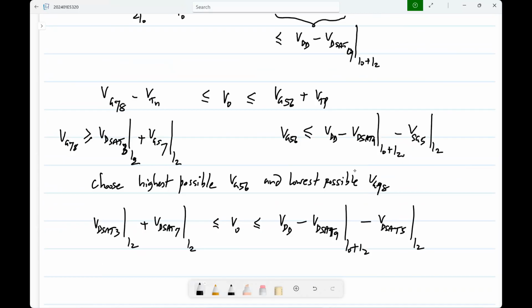So, one big difference between this and the other op amps is the swing limit. Okay. You just have two transistors on the top and two transistors on the bottom. It's also sort of symmetrical, right? Whereas the others were skewed to one side, this one is symmetric. Okay. So, this is the primary advantage of the folded cascode. Okay. Any questions about these?